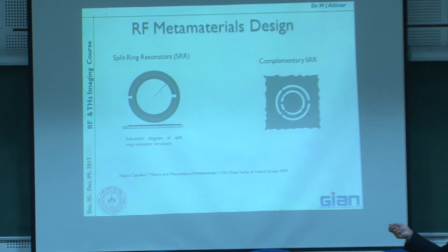Okay, so a split-ring resonator means I have a normal substrate, the white portion is dielectric, and this gray portion is metallic. So I have a normal substrate, a normal microstrip line, or even any substrate, and I make this structure. I can call it a split-ring resonator, and you can show by analysis that it will have negative epsilon and mu at some frequency. But anyway, even if you don't want to show it, that's fine. We say it's a resonator. At some frequency, it will resonate.